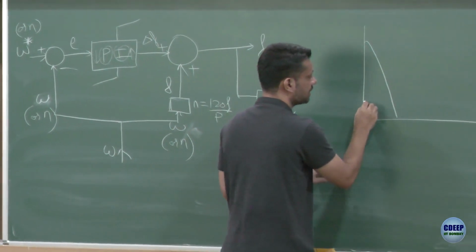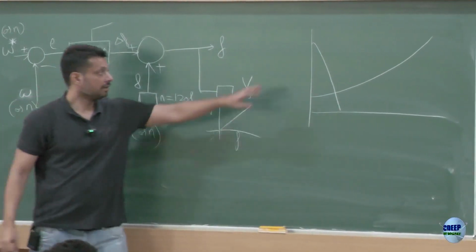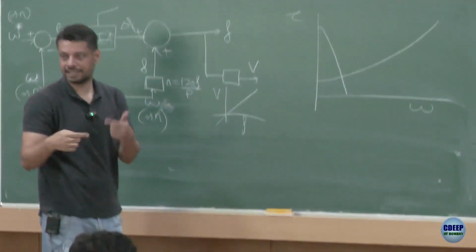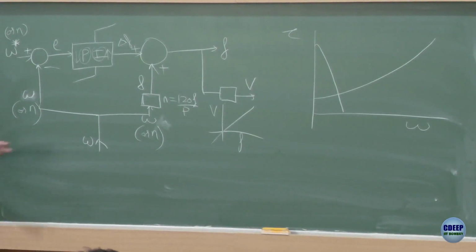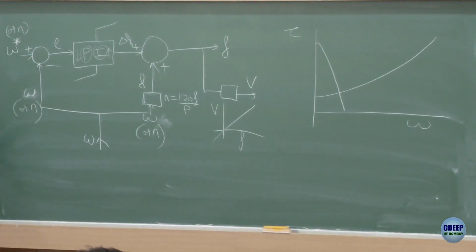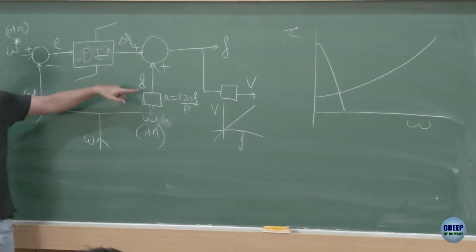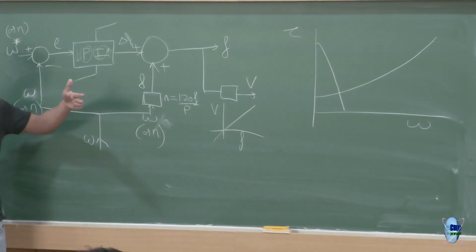this first characteristic. You have applied this first characteristic, right? This is the torque-speed curve. You have applied the first characteristic, and the motor starts rotating, right? As the motor rotates, your speed has become a little bit more. Let's say it has gone from 0 to now 50 RPM. Now 50 minus 1000 is still positive, so it would still be integrating, still adding a delta F to the frequency corresponding to the 50 RPM, which is the existing frequency.